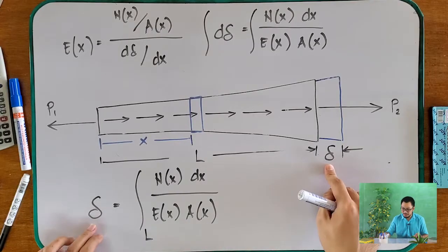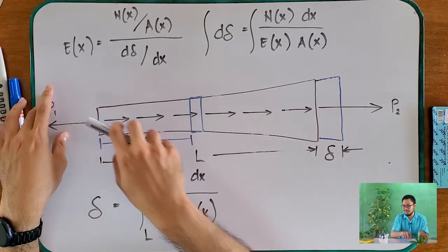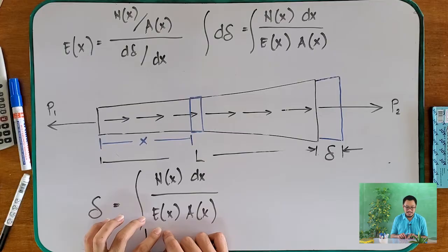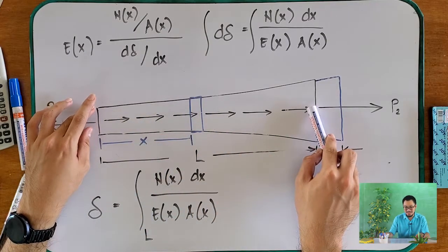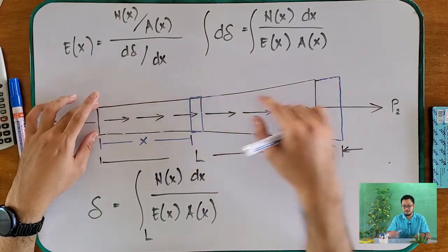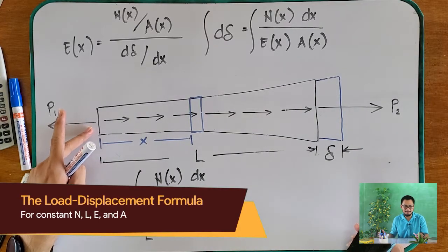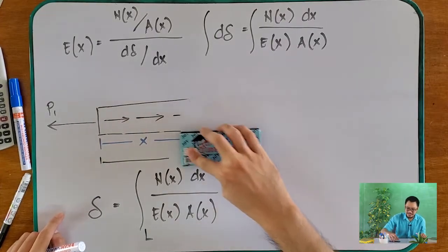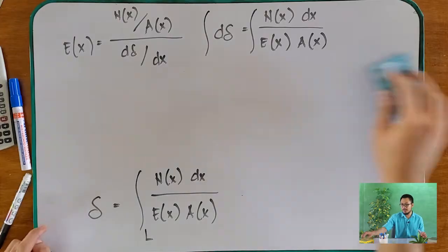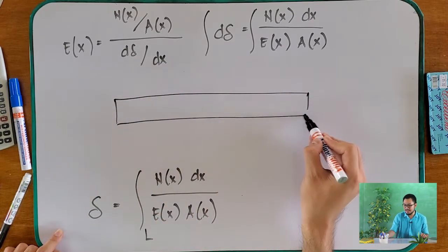So this is your general formula when you are going to solve for the deformation of this kind of beam, if you have a distributed loading along x and a modulus of elasticity that varies along x, which is usually not possible, and an area which also varies along x. But how about, sir, if it is not this kind of beam? We are not familiar with this kind of beam; it seems unusual. The beams we know are straight, and they are not tapered, right?